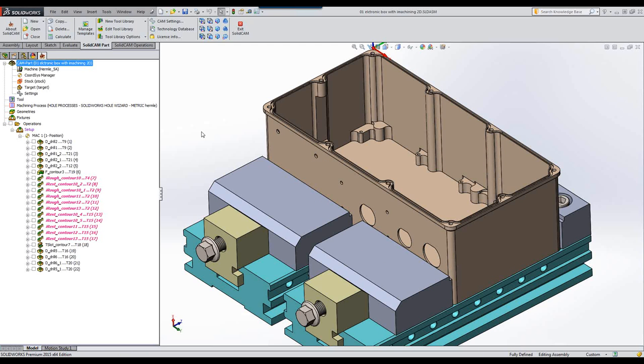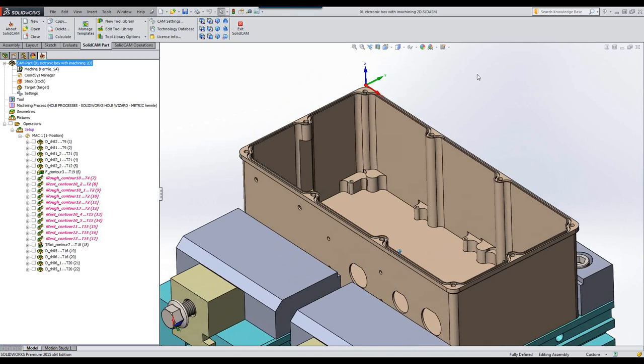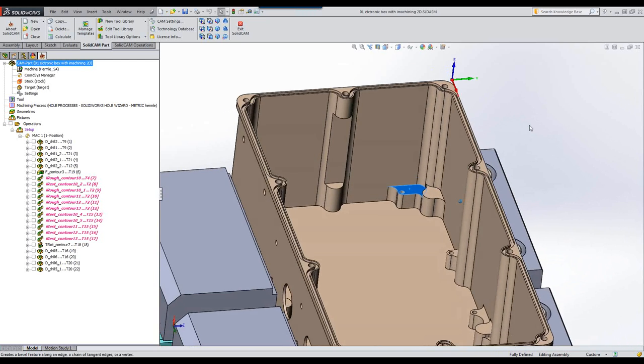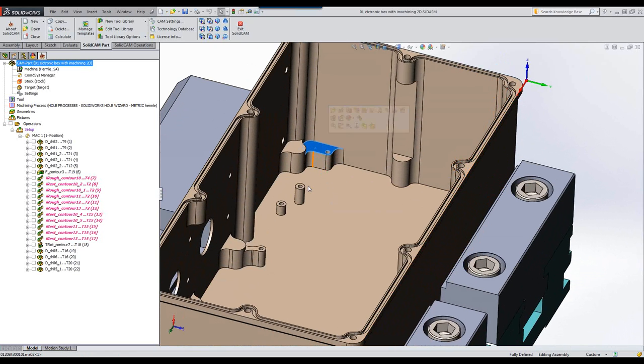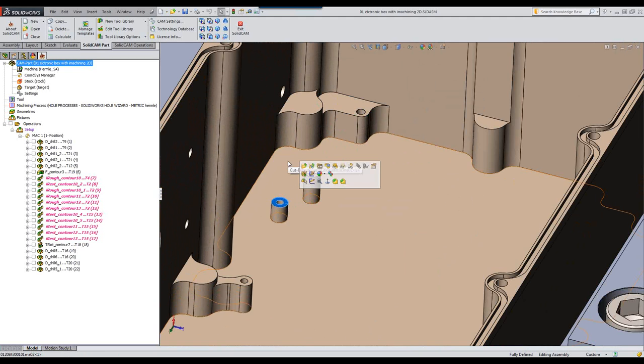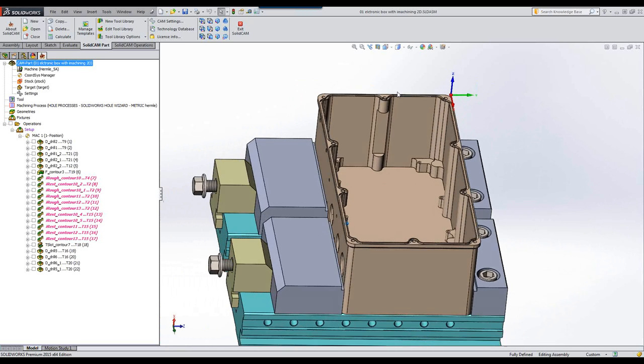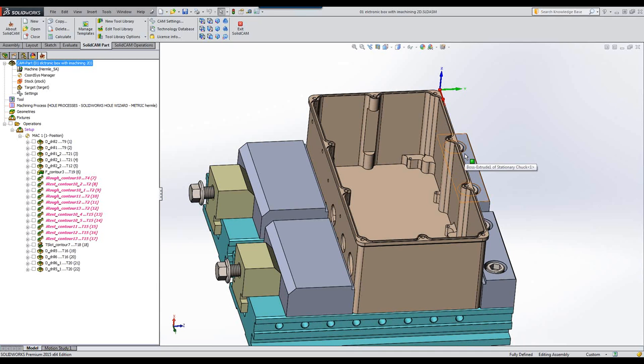However, when we did this in iMachining 2D, for every single step that we had to go down, you can take a look inside the part itself. We have a level that goes from here up until this level over here. From here to here is a total of 95 millimeters. We have another step that goes down to there, and another step that goes down even lower than that. We even have these two steps over here, which are not the same height either. So in order to do iMachining 2D for all of this, I have to do several different roughing operations to work efficiently around those areas and get to each depth individually. And for each area, I need a separate geometry.